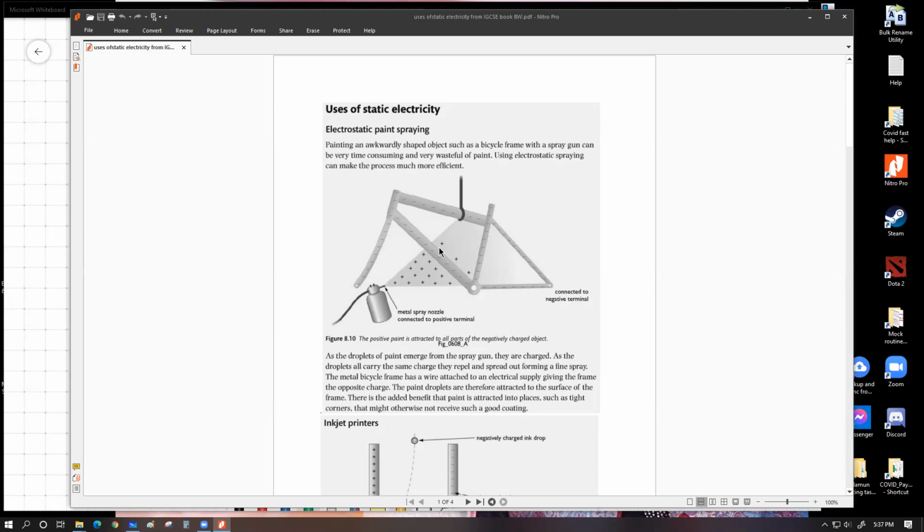I mean, painting can be done in a lot of different ways. One of the ways to do painting is by using a brush. One of the problems of brush painting is that we cannot paint with a brush with uniform thickness, because every single time the bristles are there, you're going to have a little bit of low thickness, and in the gaps in between the bristles, the paint that is left on the surface would be slightly thicker. So brush painting cannot ensure a perfectly uniform thickness, and it's also quite slow compared to spray painting.